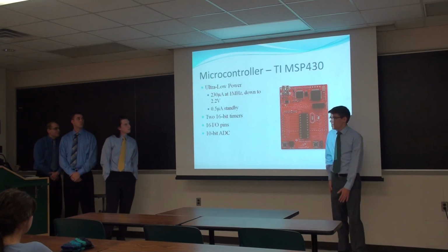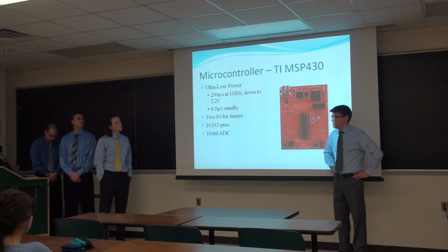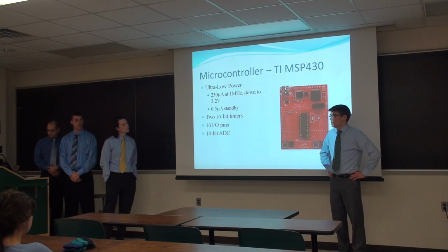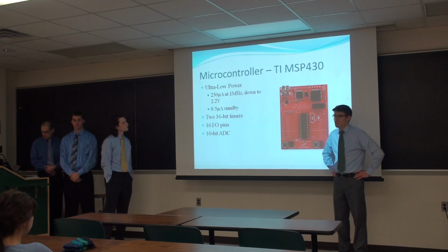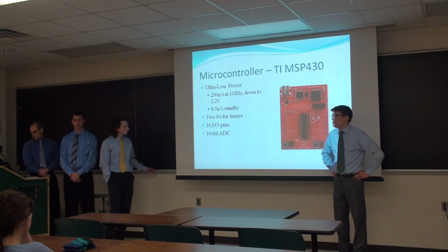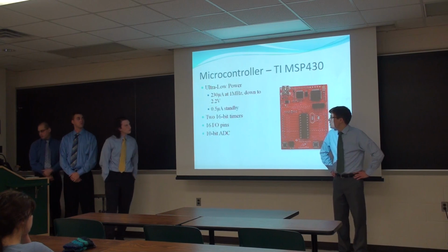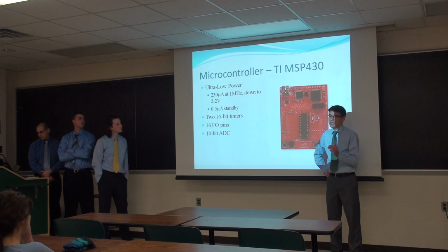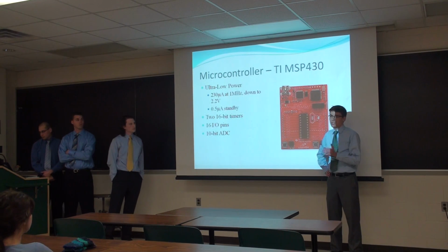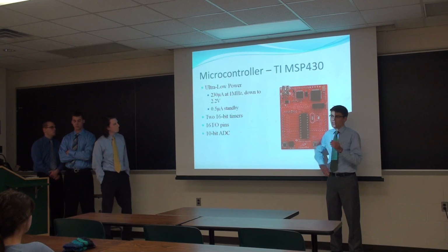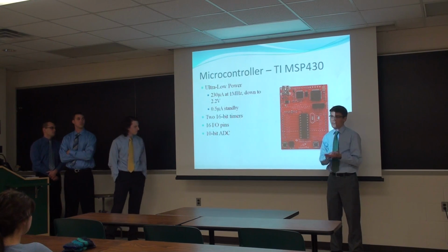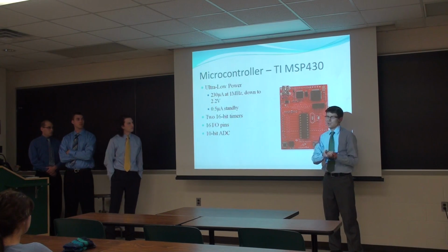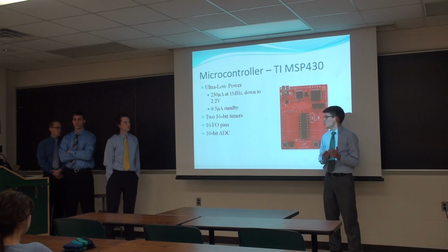At the heart of our design, we selected as our microcontroller the TI MSP430 2553. The thing that really drew us to this microcontroller over competing models by companies like Atmel was the fact that it's highly low power. As you can see, it can run on half a microamp in standby mode while still maintaining a clock signal. We're going to use this so that the user doesn't have to reset the time after turning the device off and back on again, which is important because our sponsor wants us to run for over a month on 2 AA batteries.